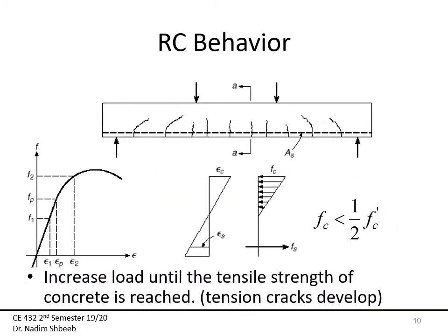So what happens now if I increase the load a little bit? If I increase the load a little bit and I go above the rupture strength of concrete, which is in this portion right here, you are starting to see some cracks develop. These ones in the middle, which are going upward, we call flexural cracks. Here we have a mix of flexural cracks plus shear cracks, and we will talk more about that when we start discussing the design of shear. But for now, the flexural cracks look something like this, which is this portion right here.